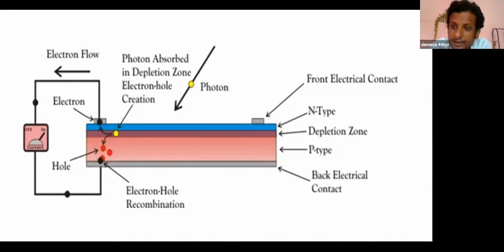That incident light breaks the thermal equilibrium of the junction. The free electrons in the depletion region will quickly move to the N-type side of the junction. Similarly, the newly created holes on the P-type side cannot cross the junction because of the same barrier potential of the junction.